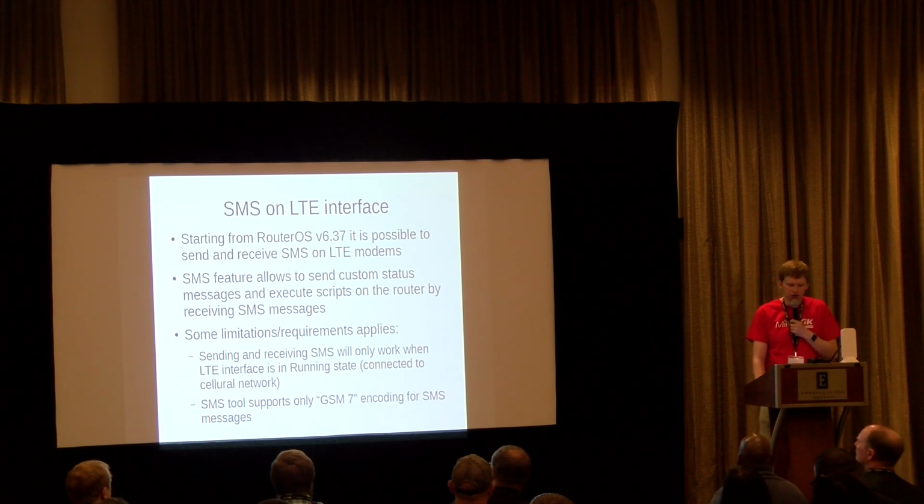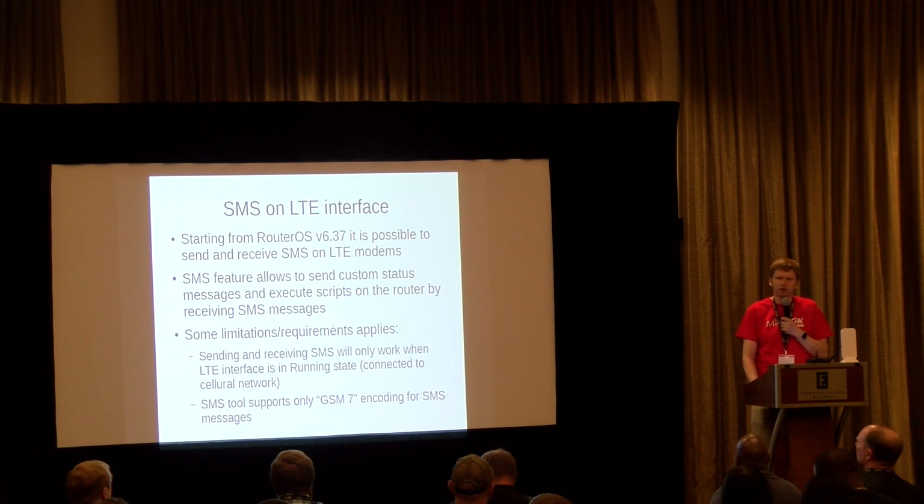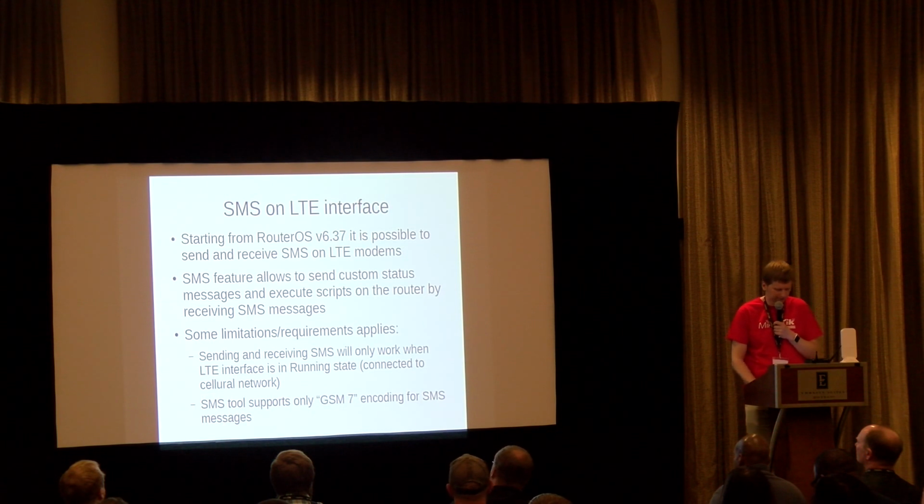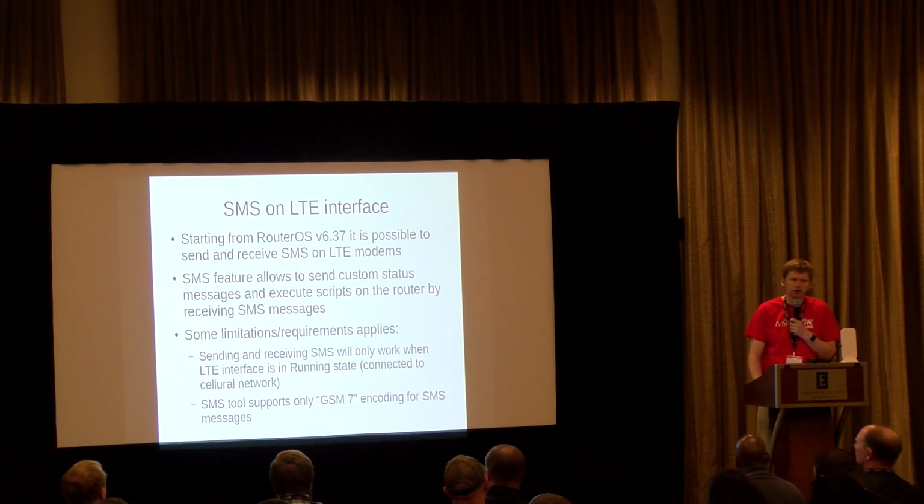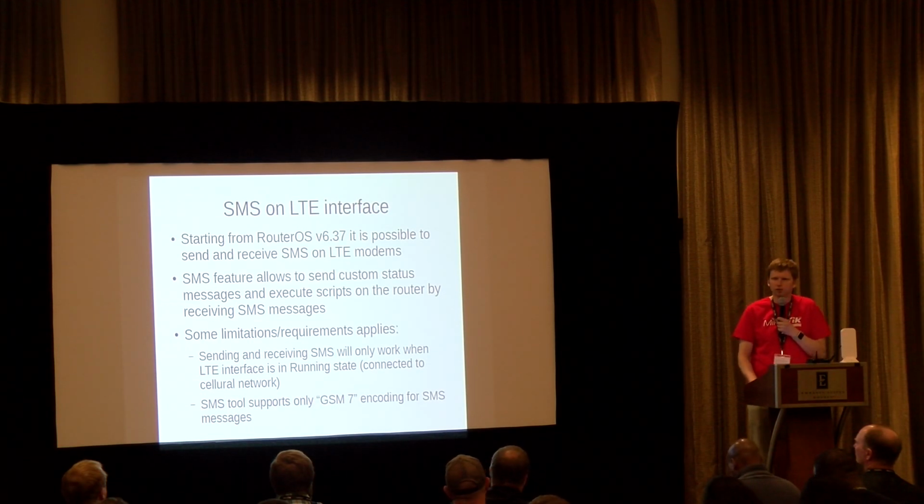But there's a limitation for the LTE interface. This only works when the LTE interface is running in the connected state, so it needs to be connected to the tower to do that. And a second limitation is that the SMS tool supports only GSM7 encoding, so no emoji support for you.